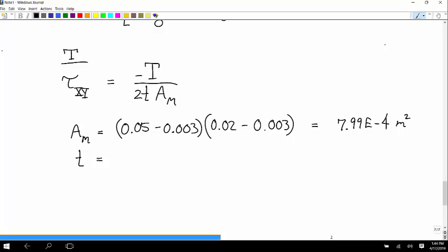Remember, for calculating the stress due to torque in thin-walled cross sections, we can't distinguish across the wall. The wall has a single value, and because it's thin, that value doesn't change very much. So this is just going to be 0.003. Yep, that's right.